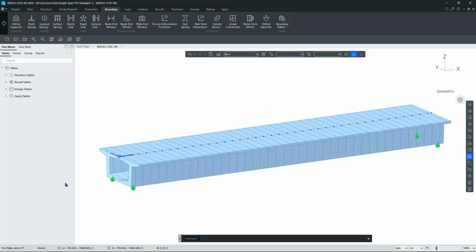The second option is defining the tendon profile in AutoCAD and then importing it into Midas Civil. The third and final option is to define the tendon profiles with respect to the x, y, and z space coordinates, and construct that particular tendon for the elements.